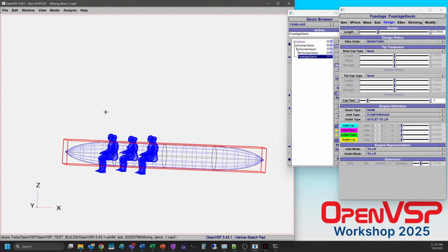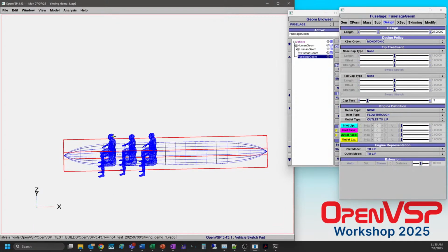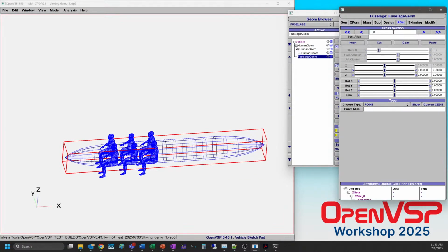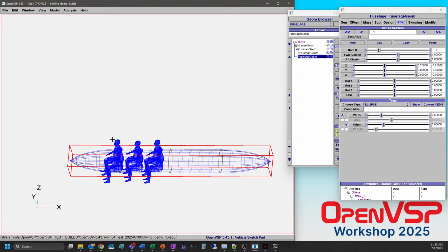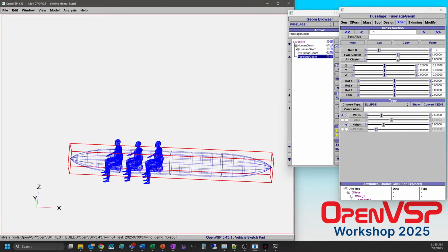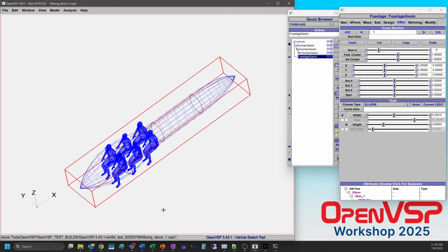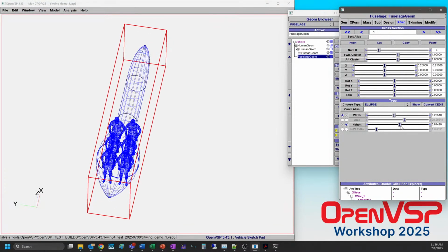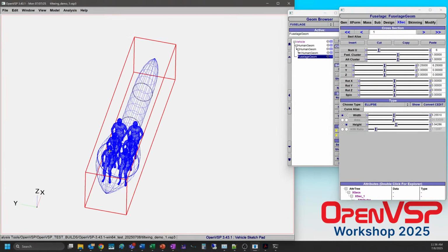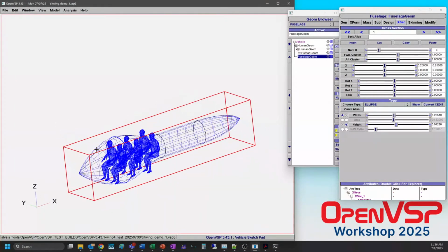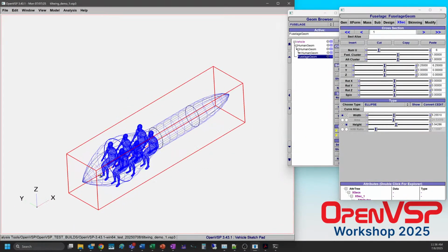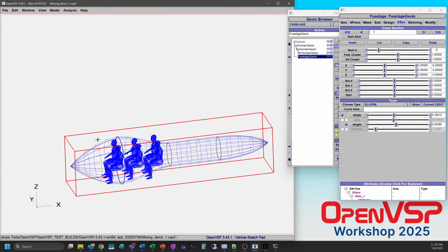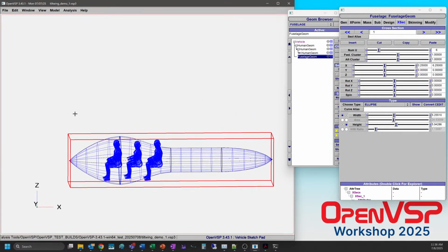As we're doing this, we need to adjust these cross sections inside. Right now, the tip is a point. We come out to the next cross section, and that's essentially this cross section. We can adjust the width, you can see here from the front, and we can adjust the height, because right now we're set to an elliptical cross section. An ellipse is a fair place to start. We could change the shape of this, and we probably will later, but for right now, let's stick with that.